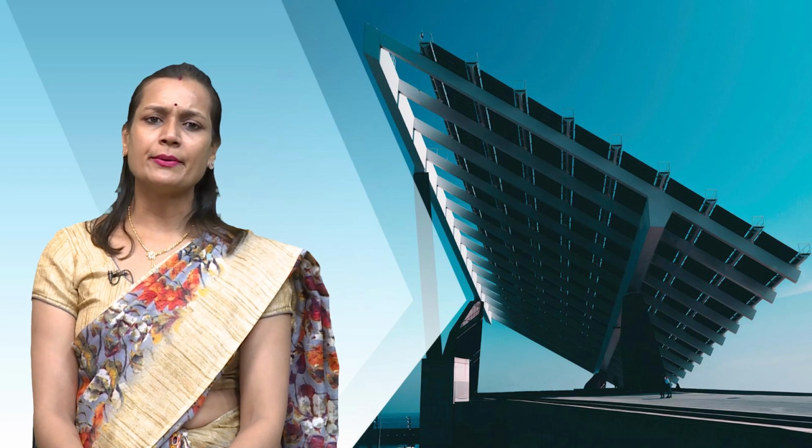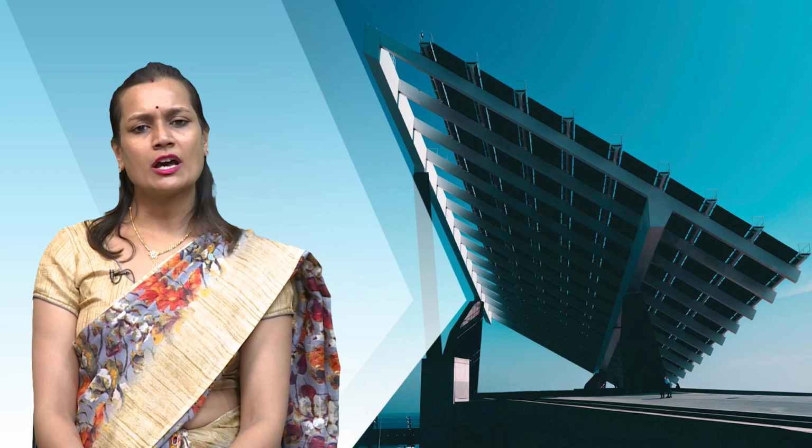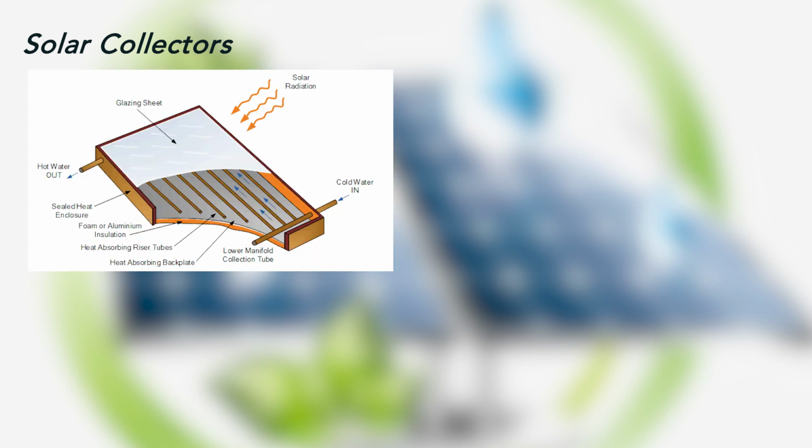Here is how a typical solar water heating system works. What are the main components of solar water heating systems? Number 1, solar collectors. These are the key components of the system and come in two main types. Flat plate collectors, number 1. These are the most common type and consist of an insulated box with a glass or plastic cover, a dark absorber plate usually made of metal and a series of tubes or channels through which the heat transfer fluid flows.